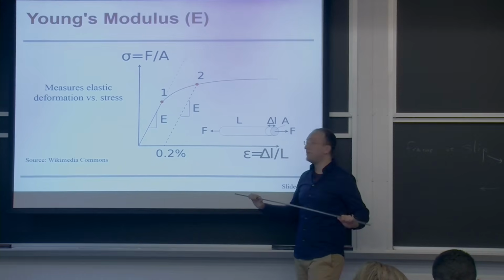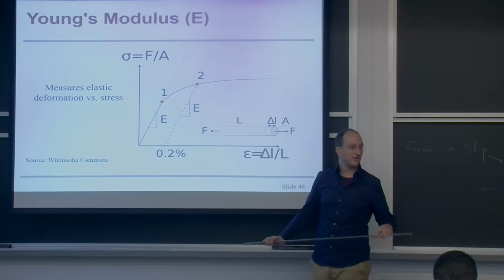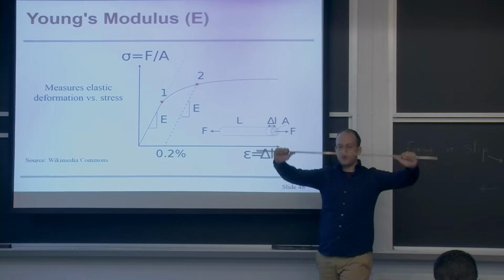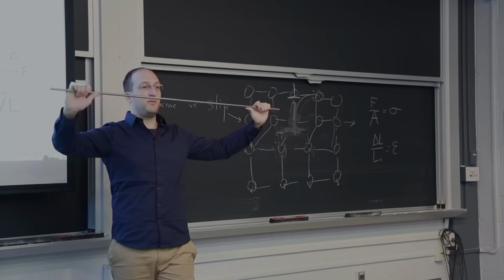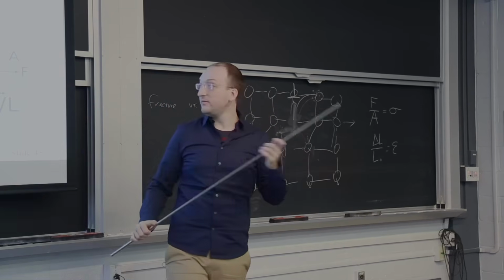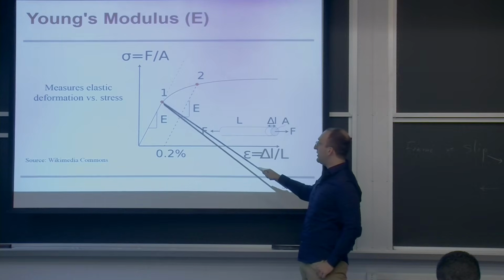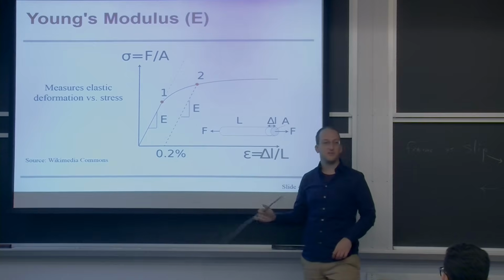So the opposite of stiff I would call compliant, not soft. This is one of those tricky things. Something that's stiff, you try and flex it and it won't flex. Something that's compliant, you put a little bit of force into it and it undergoes some amount of strain. And that slope right there between the stress and the strain we call the Young's modulus.